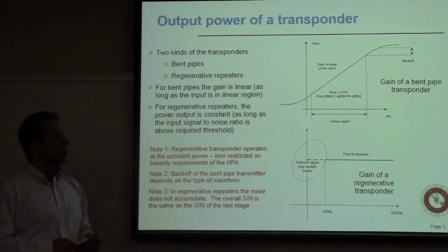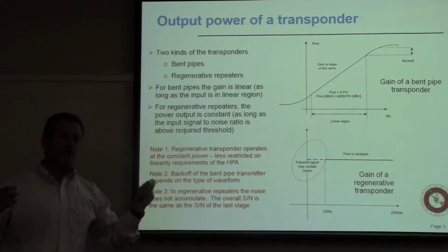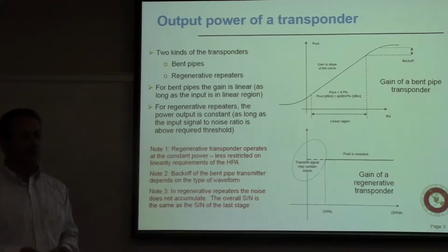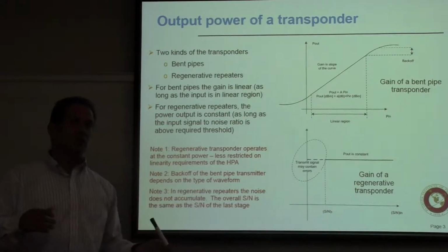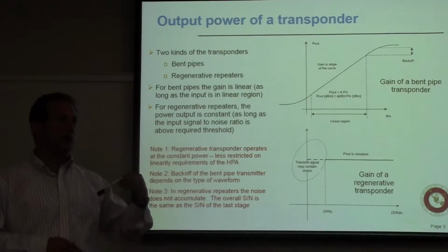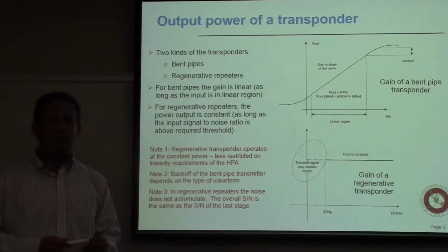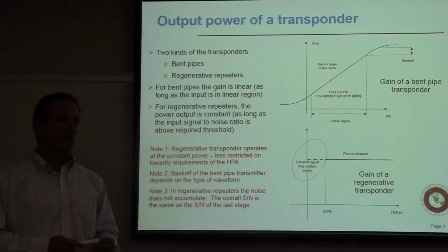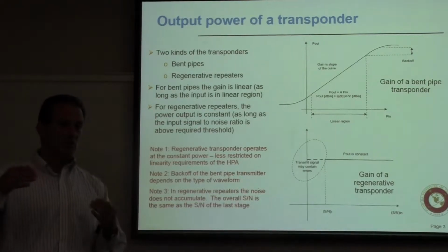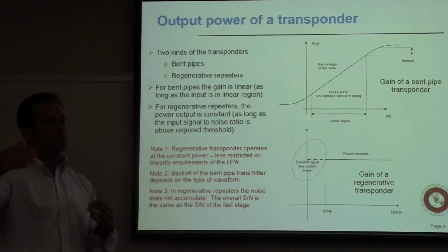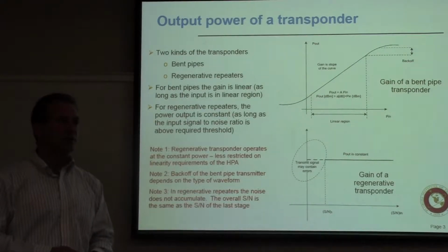below, so that when the signal is at its peak power, it is still within the linear region of the satellite. Now, for this very reason, in satellite, I don't know if you've sensed that from what we've been talking about so far, but the link budget is a big deal. You're fighting for every dB. You have huge losses, and every dB helps. And anything that you can do to minimize this backoff and allow you to operate with a higher transmit power is being done.